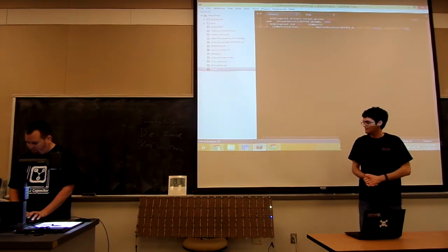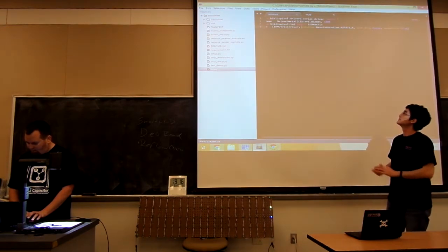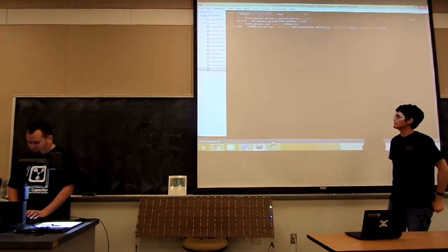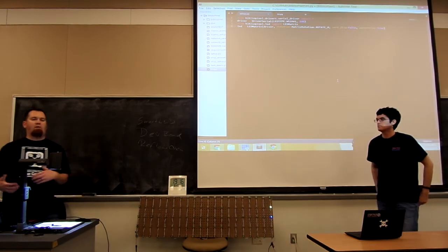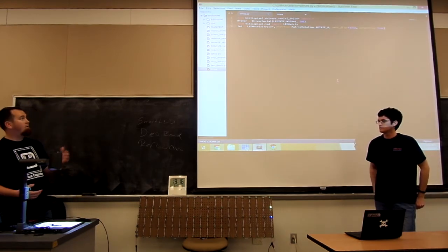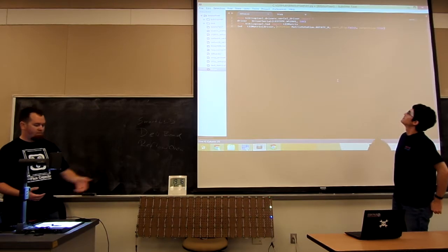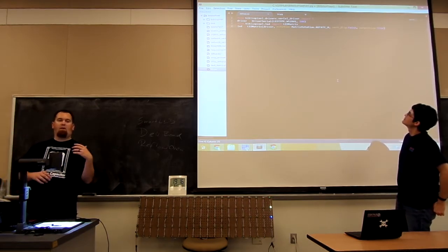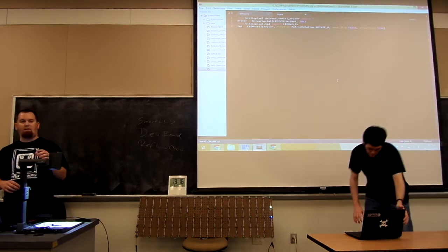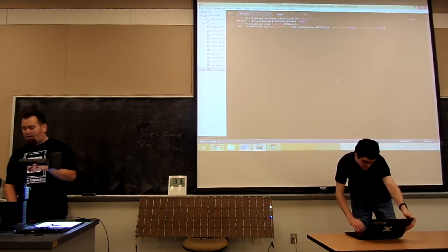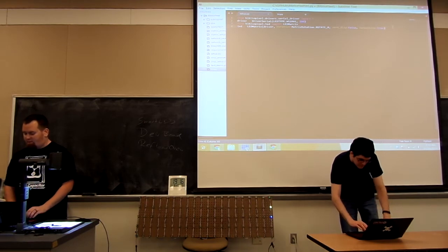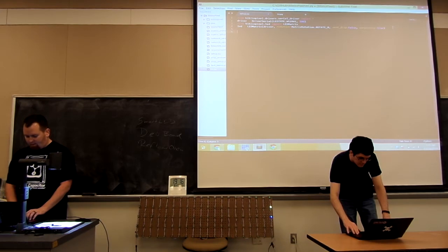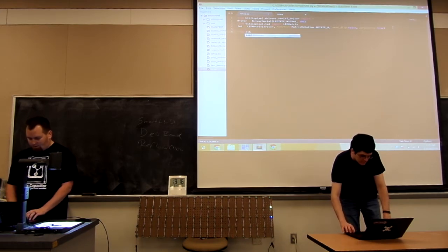BiblioPixel works with a driver model, which allows you to pretty much just write your animations once and then fill in the driver to output to whatever you want later on. So I'm using driver serial, which is for the All-Pixel specifically. It's a USB CDC serial communication. It has full 12 megabit per second throughput. And so I instantiated the driver, instantiated the LED class, which handles all the matrices and whatnot. And then, let's see, we'll pull in some animations.